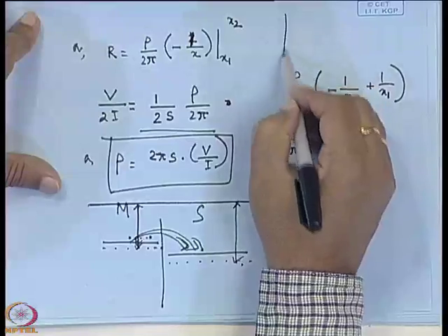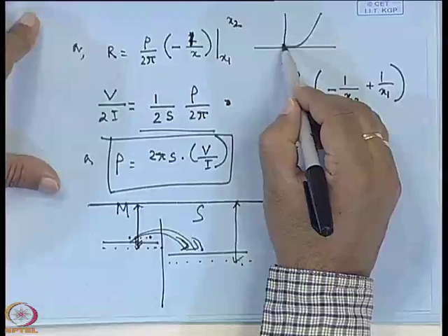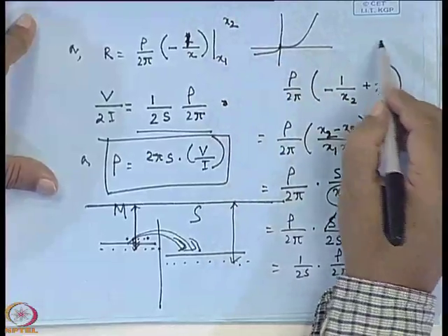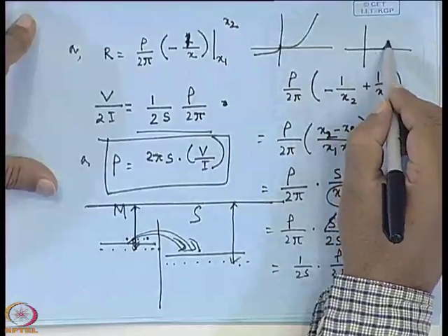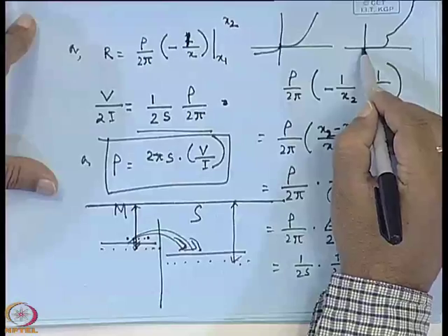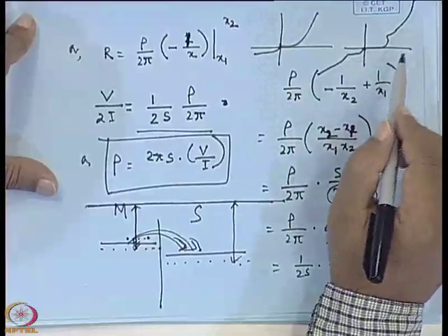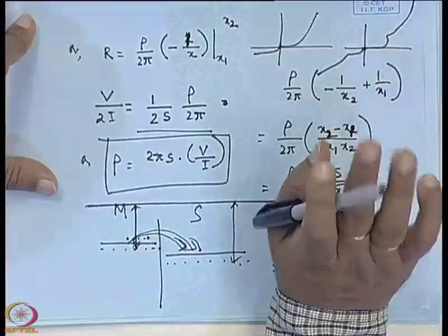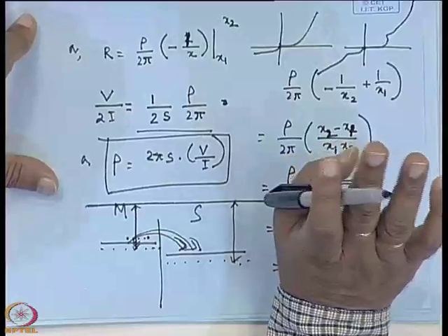Under such a condition, is it Schottky? Yes, it may be Schottky, it may not be Schottky, but it is non-ohmic in nature. Sometimes you will find that the actual Schottky curve is like this, but in some cases you will find that it is like this or like this. Then this is not a perfect Schottky. This is non-ohmic in nature.